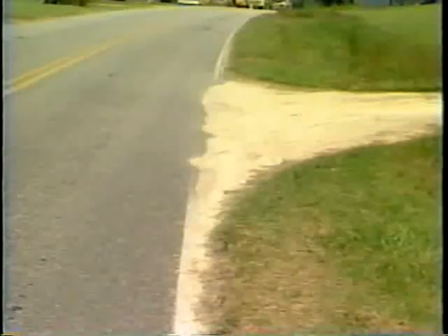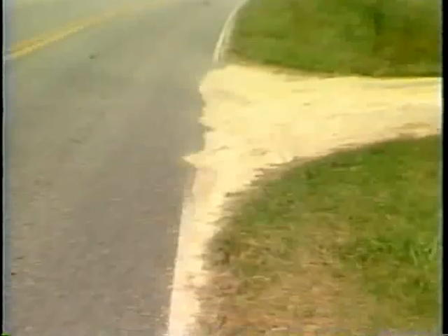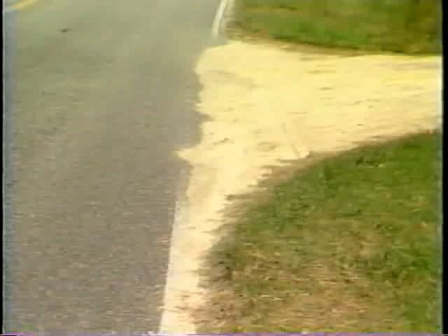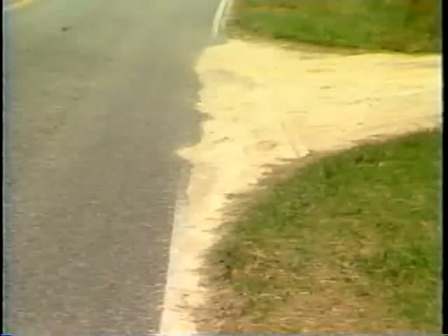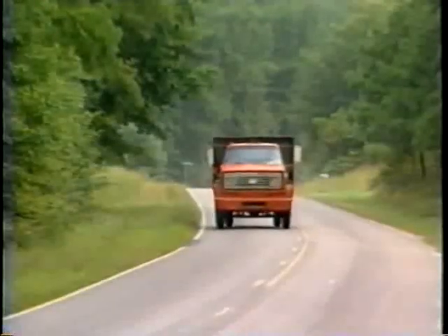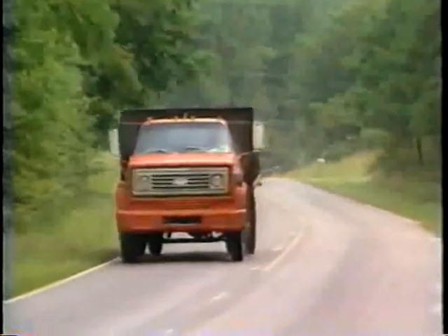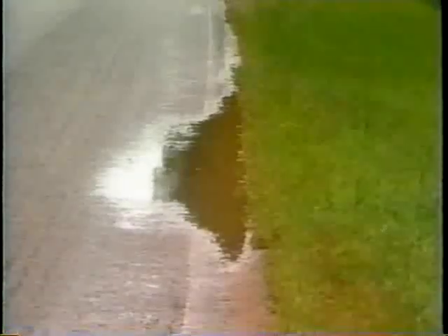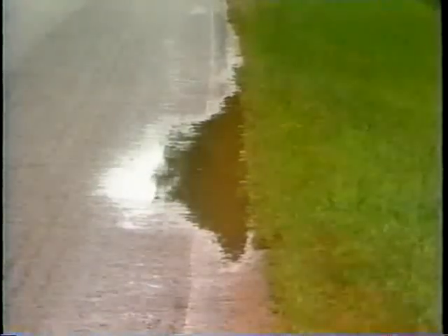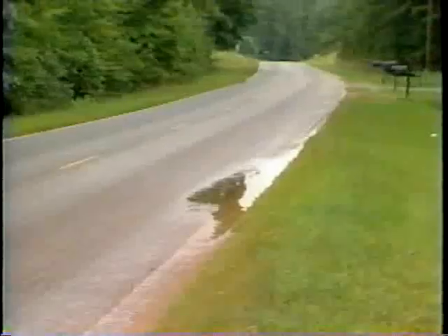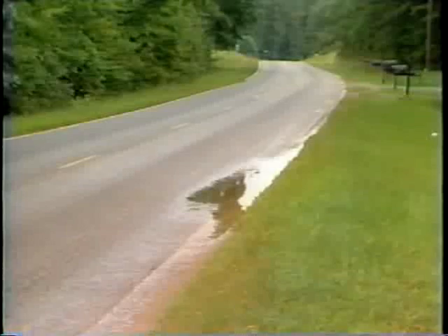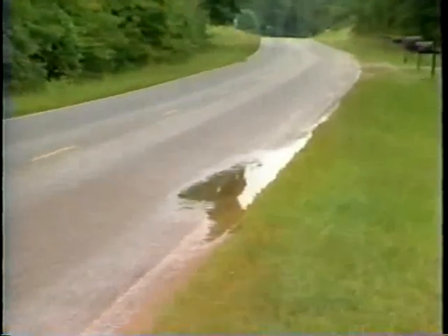High shoulders can be caused by soil material being washed away from driveways or other intersecting roads and collecting on the adjacent shoulders. High shoulders create a problem because water will pond at the edge of the pavement. It is trapped there and not able to drain across the shoulder and into the adjacent ditches. Water standing on the edge of the pavement may filter through the roadway and down into the base and subgrade below.